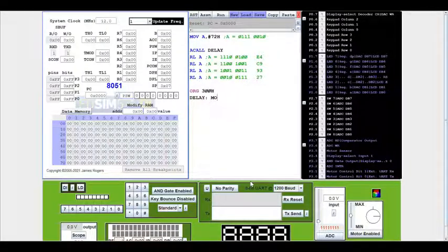Move to some register a counter value. I'm just putting it as, say, decimal 10. Then we'll decrement the counter R0, so that until it becomes equal to 0, so much delay you're getting.